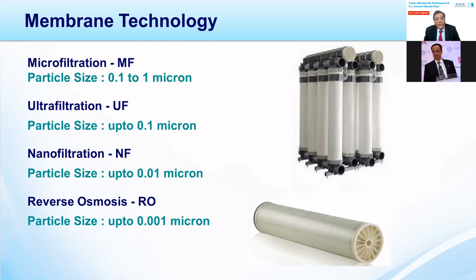Ultrafiltration is normally used if our source of water is potable, drinkable. For disinfection, we can use the UF membranes. They can eliminate microbes and biological contamination, and we don't need to treat the water through RO plants, because the RO plant will remove the TDS, and you will then have to mix it with raw water or remineralize the water.